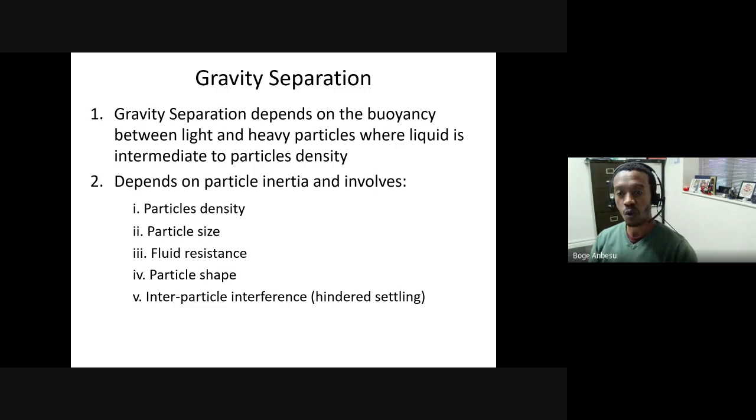If you are processing coal, it's slightly different because coal is the valuable part in any coal deposit, and the coal tends to be lighter, with a specific gravity of maybe about 1. But in coal, typically you have ash forming minerals, and those are mainly silicates, and they would have, say, a specific gravity of somewhere around 2.5 to 2.8.